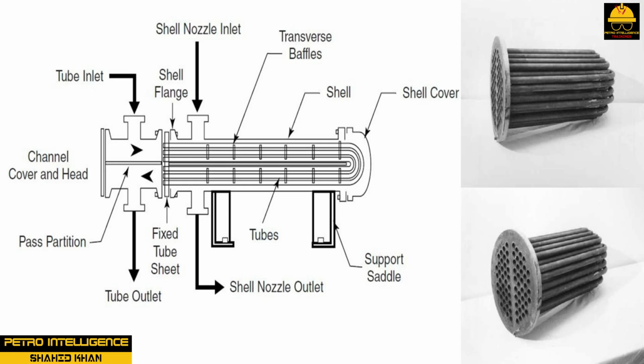U-tube. A fixed tube sheet on one end that is typically bolted to the shell characterizes a U-tube exchanger as shown in picture. The tube sheet connects a series of tubes bent in a U shape as shown in picture. The ends of the tubes are secured to the tube sheet. This design limits the total number of tubes that can be used when compared with a fixed head. A channel head directs tube flow across the body of the exchanger twice.